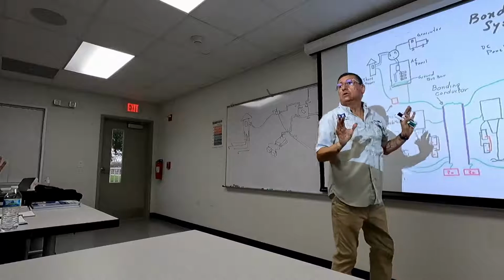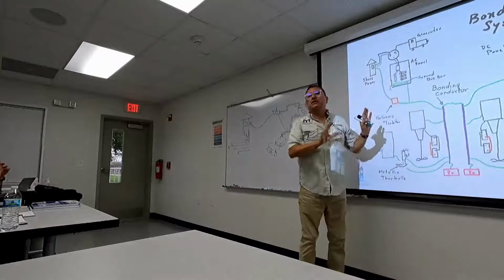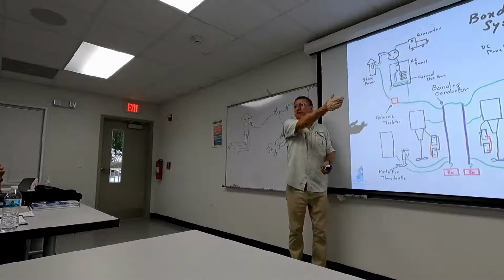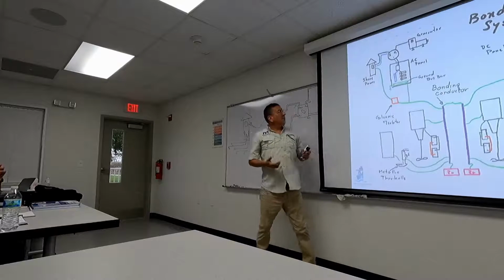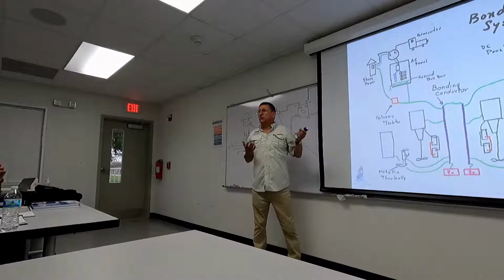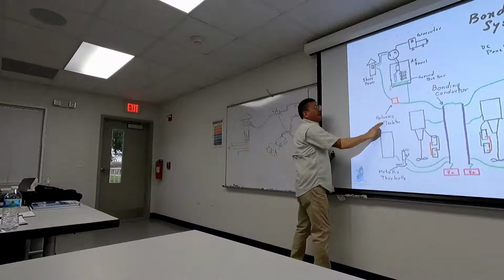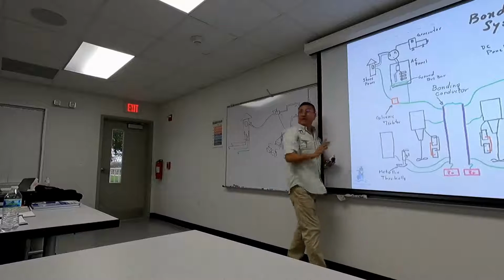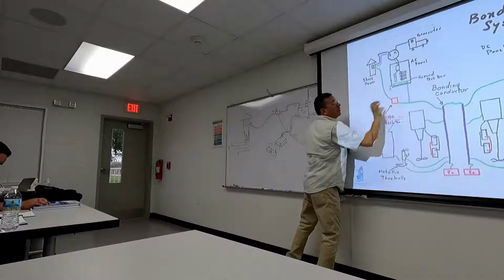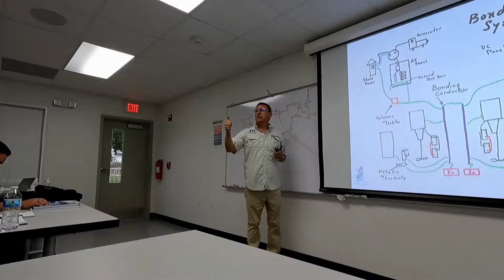This is a small boat because I have a single phase boat, like Danny said. In that particular boat, I don't have an isolated transformer, but I have a galvanic isolator to protect the intrusion of bad currents in my boat. Good? That's clear? Yeah. All right.